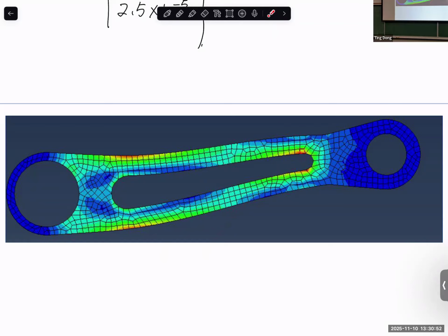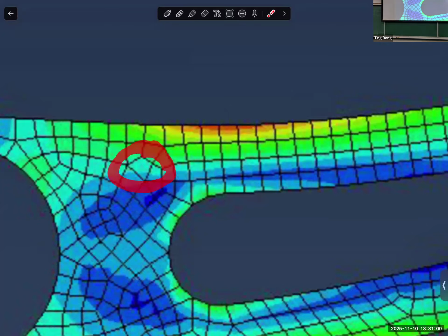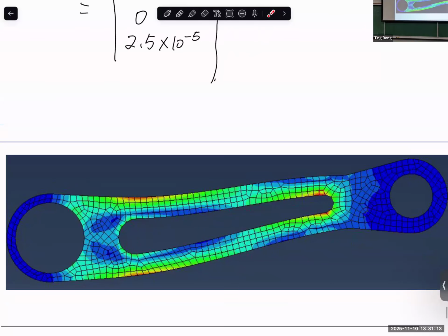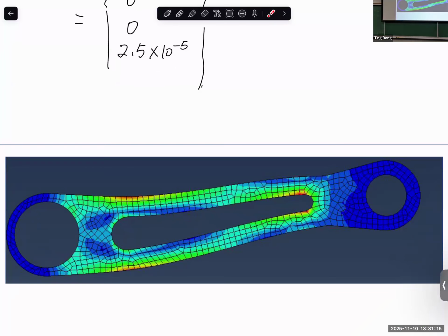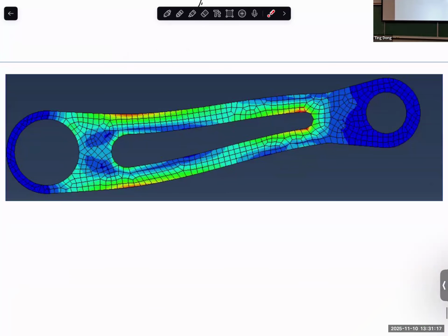The four edges do not necessarily run parallel to the coordinates, and you can see that some of the elements are not really rectangular, just four-edge quadrilateral elements. The interior angle does not necessarily have to be 90 degrees. So in this situation, we still need to solve the problem. What we need to do is the isoparametric mapping, which is in chapter 7.